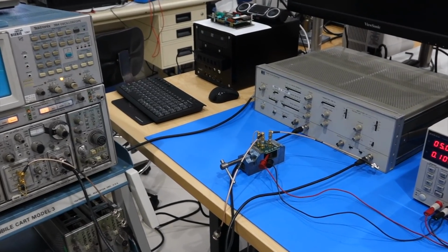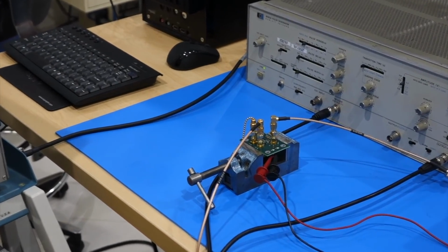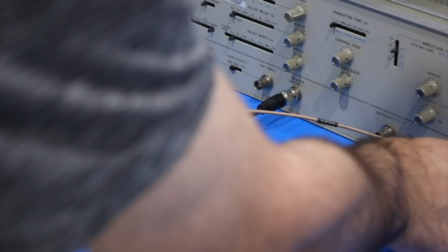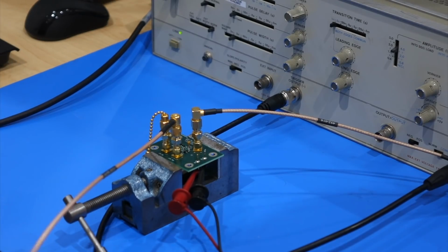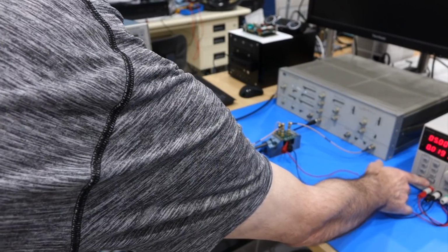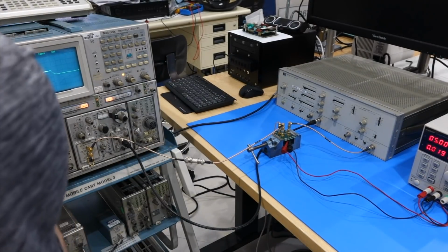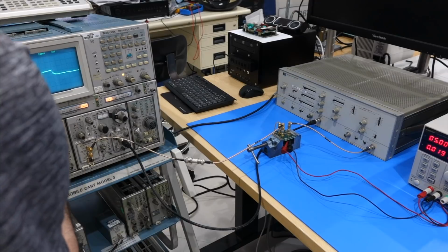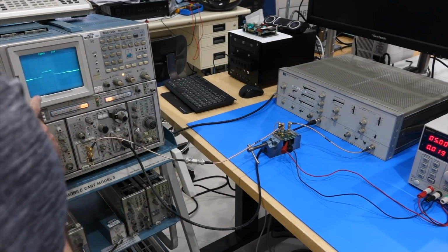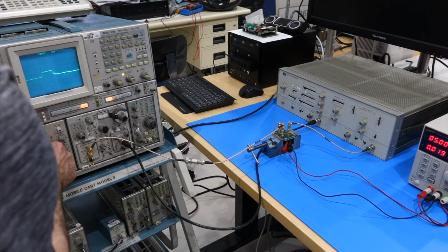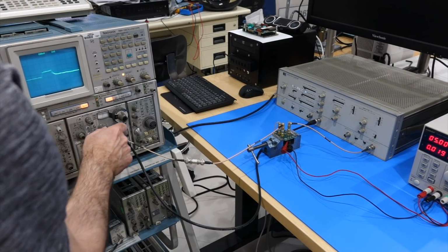So we are approaching the big moment here. I have hooked up the circuit. I am just coming in from right here with my 2 nanosecond pulse and see if I get the inverted pulse. And turn the thing on. Aha! And we do get something. We get a positive pulse with the wrong amplitude, but the circuit is definitely fast and doesn't oscillate. It's just I have the wrong settings somewhere.